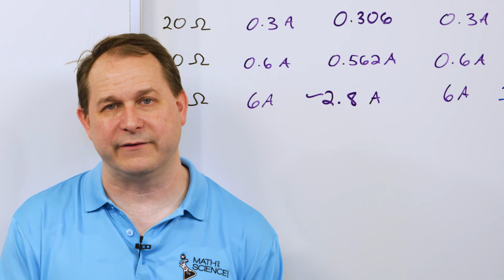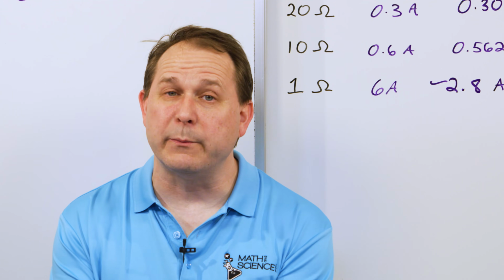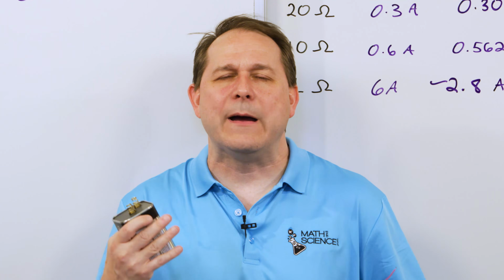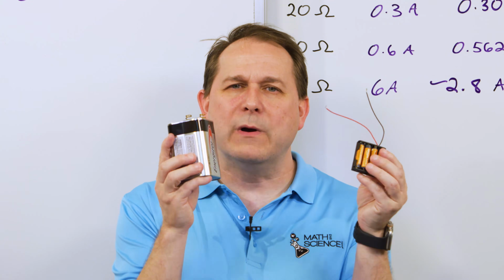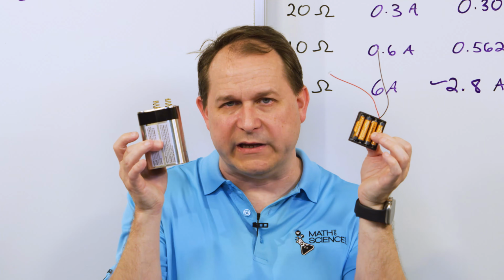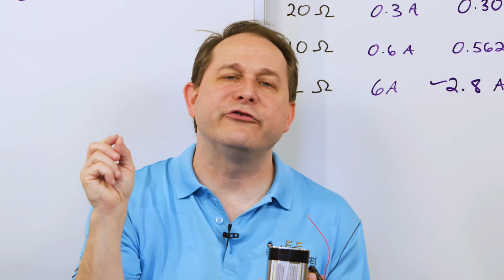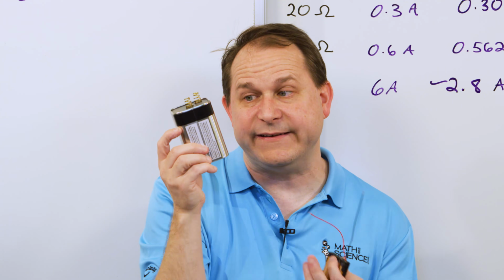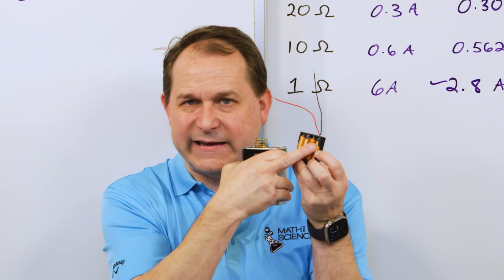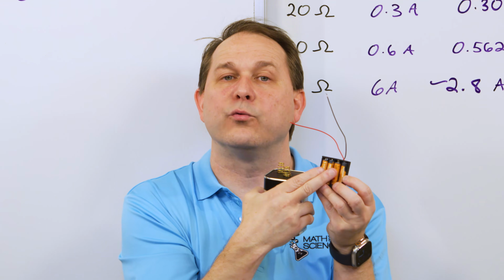Now there's one more thing I'm going to talk about here that we usually save for a little later when we get into more detail with circuits. Another way of thinking about this, I've described it in terms of how many electrons it can supply. But I don't want to get into it now because it's a little too early. If you draw the circuit equivalent of an actual battery, you can model it as a voltage source, but also with some internal resistance. In other words, this device has physical objects inside of it that have resistance. The chemical reaction, and also the wrapped foil inside of it, has resistance as well.